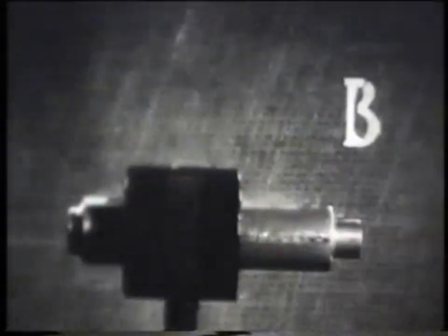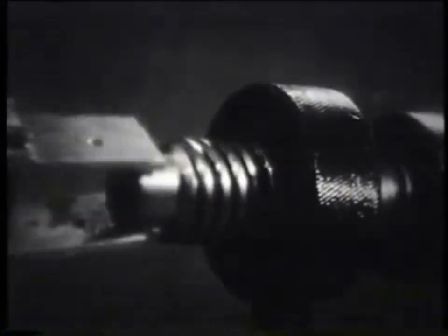A kinematic pair of the fourth class of the PV type allows 1 translational and 1 rotational movement of the link. It is called cylindrical. The spherical joint with a finger kinematic pair also belongs to the fourth class and allows 2 rotational relative movements of the link, and the kinematic pair of the fifth class of the type P allows 1 translational movement of the link. In a screw kinematic pair, the screw turns, and it moves along the nut. This pair is also fifth class, it has only 1 possible independent movement.